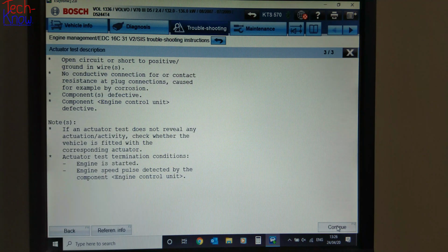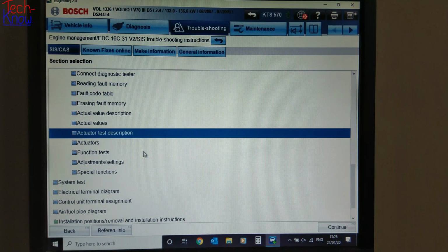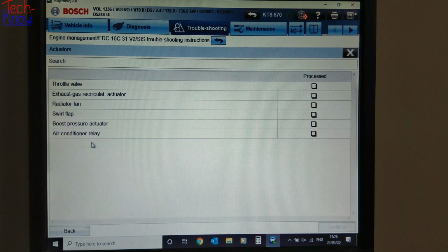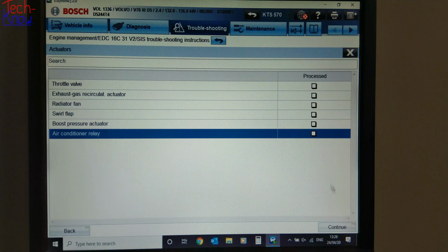And then once again with actuators here, if we click on that, the actuators on the vehicle, just as we did from diagnosis software, we can now select a particular actuator to operate, and then click new once we've selected it. So we'll say relay, continue, and then actually listen out for the switching noise, simply audible, it says there. So it's telling you what to look for. It's not just going to go and do it, it's telling you what to look for.